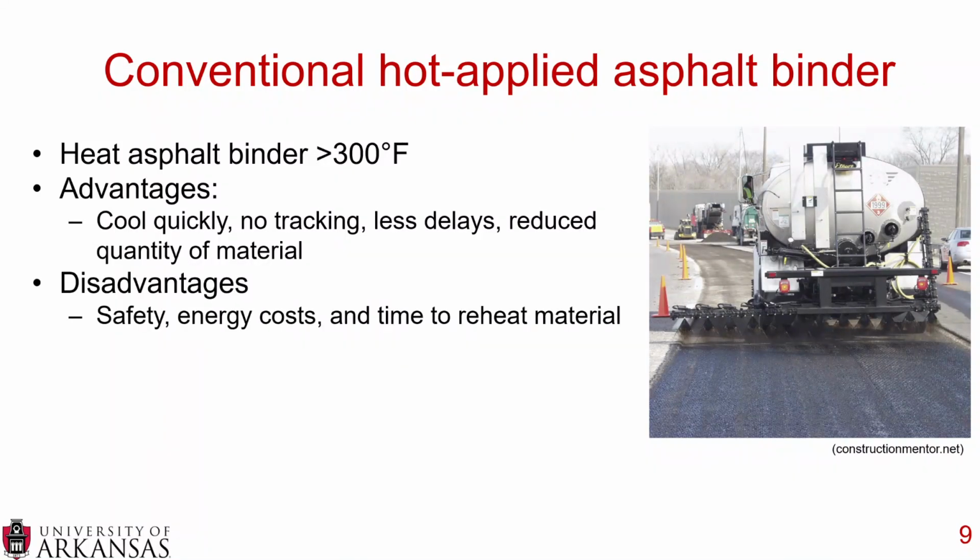Some of the disadvantages include safety. You are spraying something on a pavement surface that's 300 degrees Fahrenheit or higher, and you can imagine all that's going through pumps and pipes and such, so there is safety involved with that. You need to have a higher energy cost to heat that material and to keep it heated. And also, if the material starts cooling down, it does take time to reheat the material.